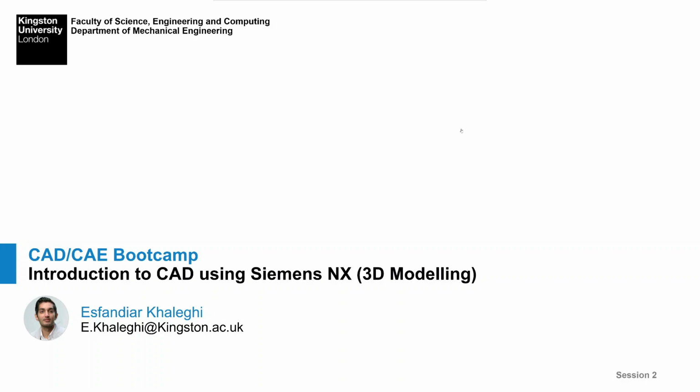If you remember, last week we started working with Siemens NX, became familiar with the user interface, and started using the 2D modeling technique with sketches. We also started a little bit of 3D modeling, just converting a 2D sketch to 3D with simple features such as extrude, extrude subtract, or extrude cut.